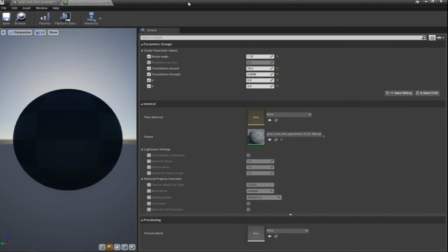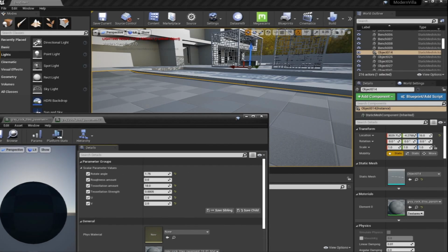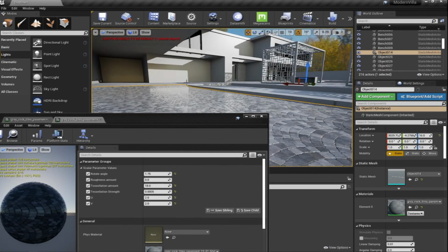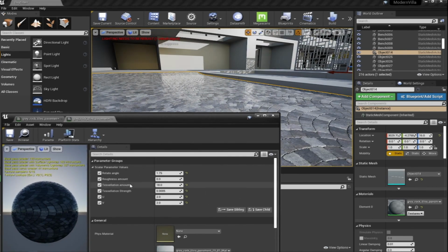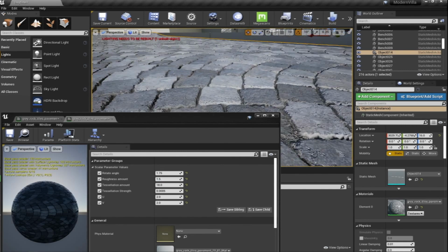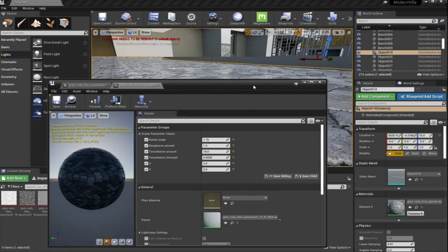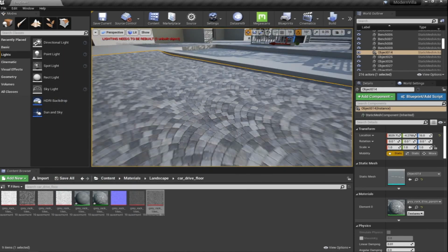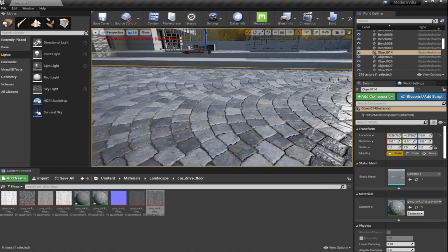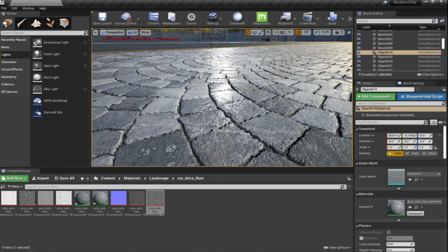Let's go to our material instance, enable the roughness amount. So you can see 0 represents no roughness at all, and we have a perfect reflection of the tile stones, but we need actually something like 0.05 or maybe 2 or 1.5, just something that will give us a little bit of glossiness on top of this material. Yeah, so for now this is enough for the displacement material to create a 3D representation of the stone.